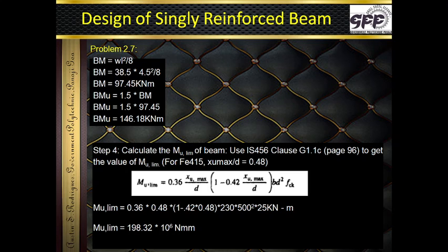Now we have already assumed the beam having the width as 230 mm, the overall depth as 550 mm, the effective depth as 500 mm, the type of steel and concrete, steel is Fe415, concrete is M20. So having assumed this, let us find out what is its own capacity of resisting maximum bending moment, in the balanced case. So knowing how much maximum bending moment it can take, if that moment is more than or equal to the bending moment which is coming on the beam, we know that this section, whatever has been assumed by us, is acceptable. So we are going to step number 4.